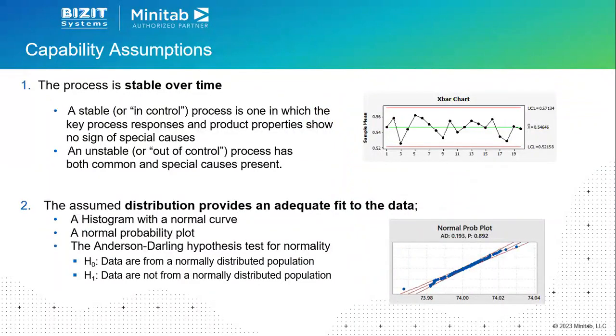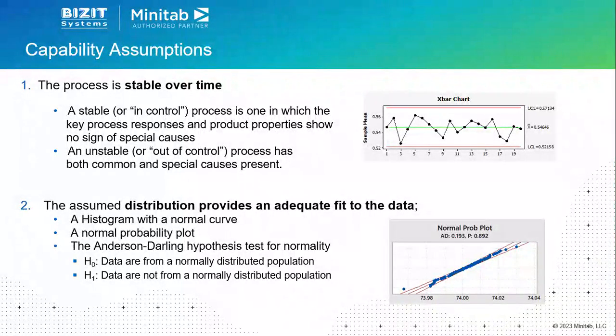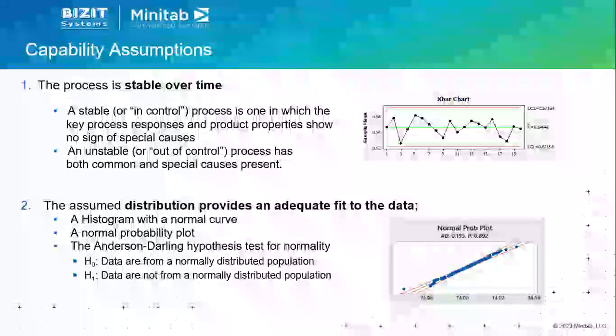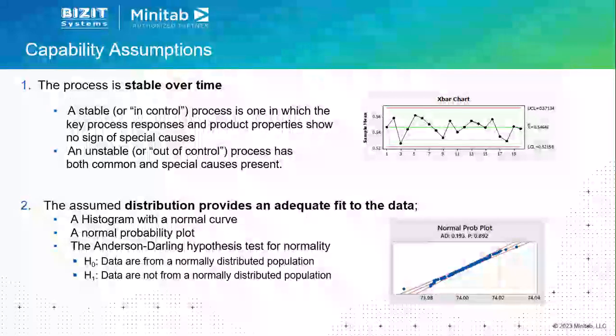So, okay, this one is an interesting part. Capability analysis is a part of the statistical technique. Capability analysis has some assumptions that you must fulfill before you rely on a CPK of 2.0, CPK of 1.6, or something like that, or on the CP, CPK, PP and PPK values. The first thing you need is that your process is stable over time.